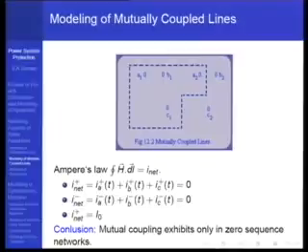Whenever you do short circuit analysis, with a tower on which two circuits are going, you will find in the data that people specify zero sequence coupling between the two circuits, but there is no coupling specified on the positive and the negative sequence. That means the coupling in positive and negative sequence is zero; the coupling is only present on the zero sequence. Let's look at the reason for that.